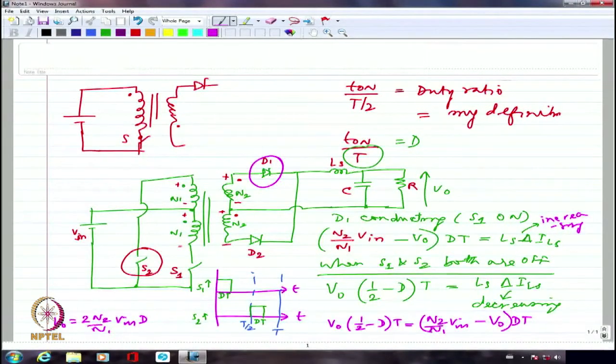And more than anything in power supply, we are worried about regulating the output voltage. So we don't want to have too much of a drop, and too much of a drop means there will definitely be a lot of copper losses across the devices. That means you have to put bigger heat sinks, and then the size will increase further and further. So you don't want to increase the size quite a bit.